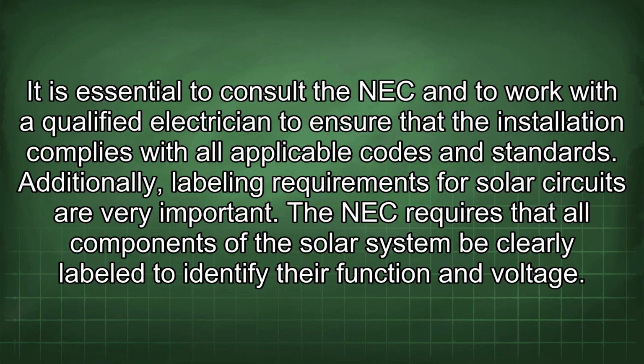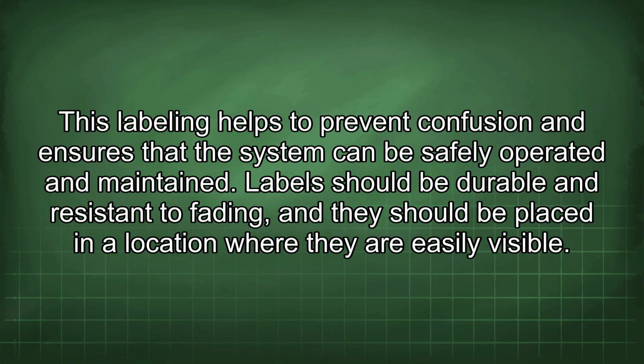Additionally, labeling requirements for solar circuits are very important. The NEC requires that all components of the solar system be clearly labeled to identify their function and voltage. This labeling helps to prevent confusion and ensures that the system can be safely operated and maintained.